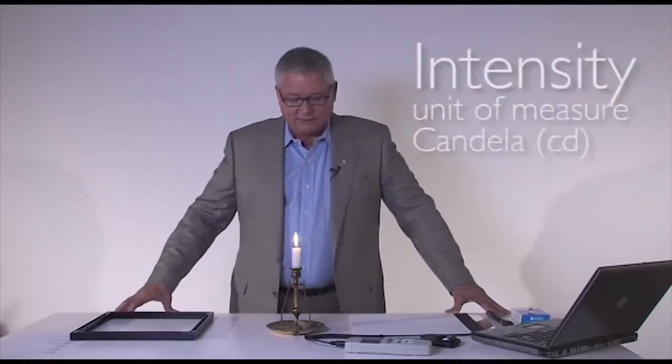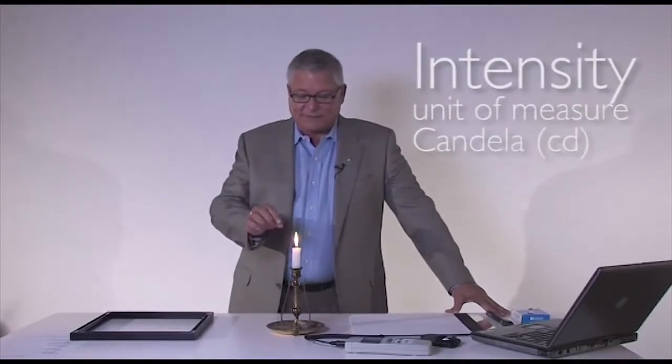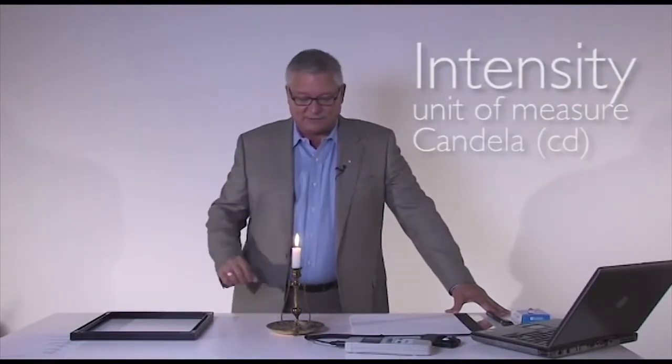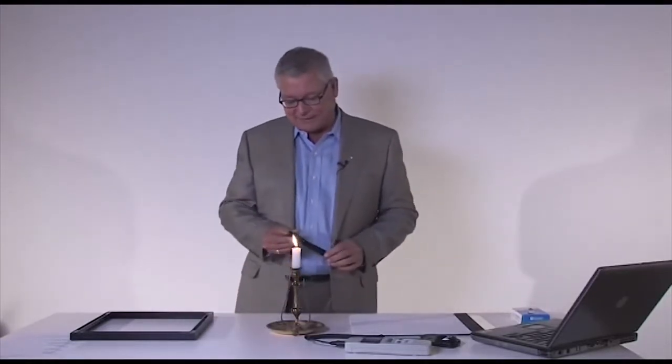In lighting, there are 5 descriptions or terms that we use, metrics we call them, to describe the light. And I'm going to demonstrate them for you now. If you take a look at the candle, this is our original light source. The candle is actually emitting an intensity in all directions. And that intensity is actually 1 candela, which is about the amount of light you get from a candle in any and all directions. This unit of intensity is used actually to describe the light output from any light source.